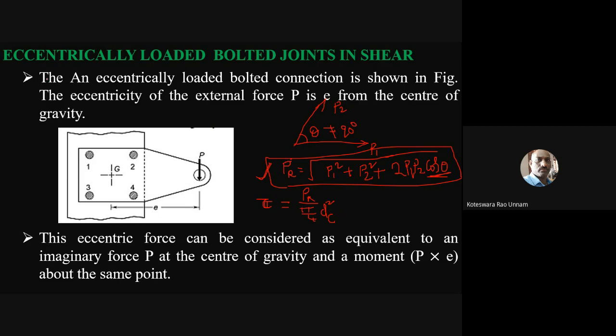Because we don't know the nominal diameter, we have to find what is the nominal diameter of the bolt. Therefore, you have to use this relation. For this, they will give the allowable shear stress value. So tau allowable, they will give, let us say it is some 100 MPa. From that equation, I know PR, so the only unknown for me is Dc. I can solve for Dc.